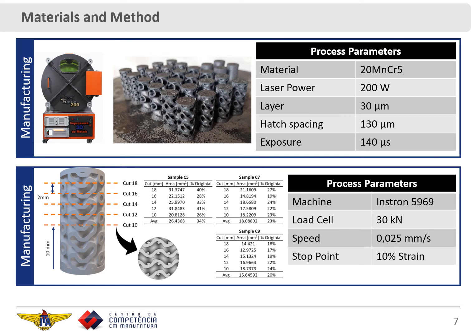To analyze the mechanical behavior of this part, we cannot use the conventional extensometers or conventional extensometry because of the complex geometries that we have to assess. So I propose a method where I made some cuts on the CAD file and measured the area that is subjected to the loading. As we can see, for each cut we have a different area. This is natural of this gyroid structure, but I choose the smaller area since this area will fail first.